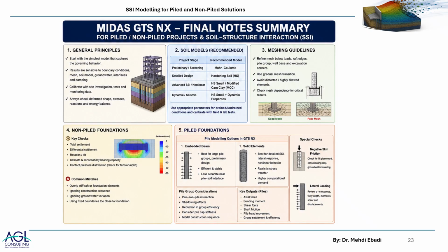It can be either linear elastic, Mohr-Coulomb, or going to advanced models like HS small plus dynamic properties. Meshing, that's very important to know where to refine the mesh and where not to. Generally, the mesh should be refined in the areas of interest, at least.